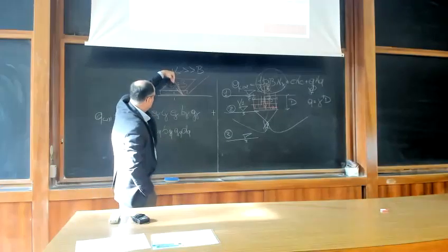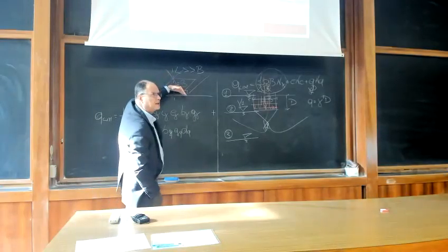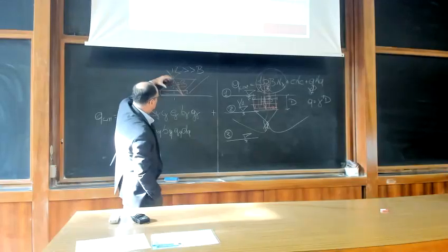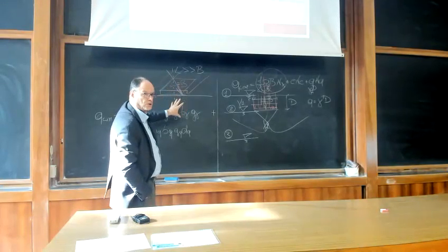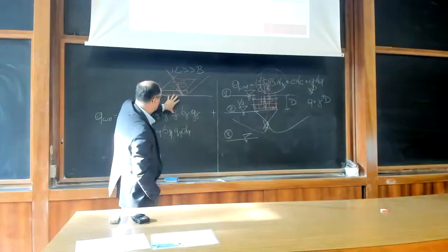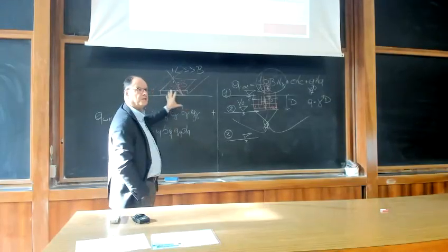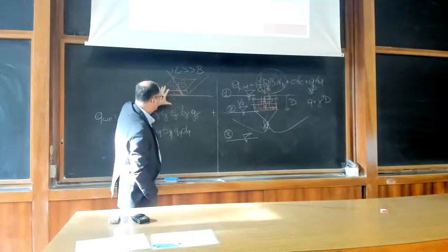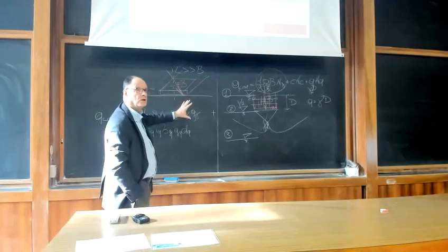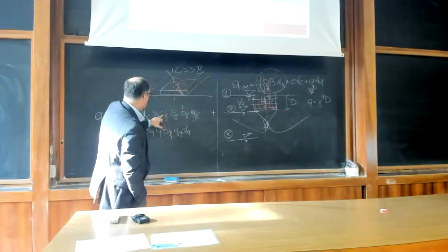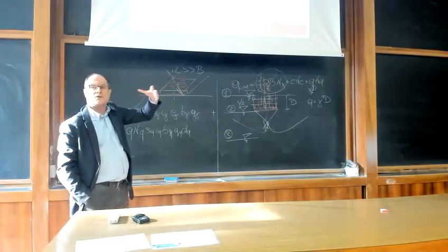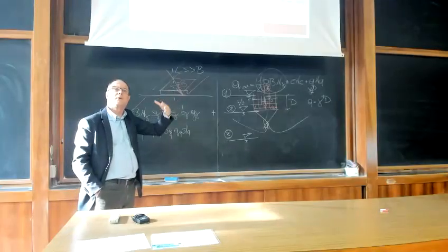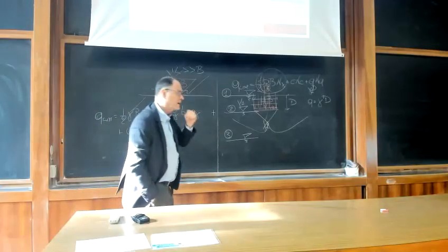Of course, if you have a resultant which is inclined rather than vertical, it is almost immediate that you will have a reduced pressure, because the soil is no longer fully involved in the capacity, but only a shallower part of the soil will provide your resistance. So typically I gamma, IQ, IC are factors which quickly become less than 1.